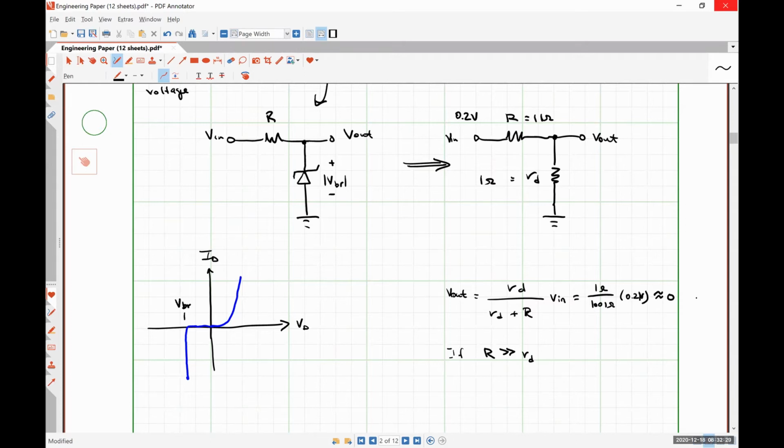So instead of pinning it at 6 volts, it would go down to say 5.4 volts or so. Conversely, breakdown voltages greater than 6 volts tend to increase in magnitude with temperature, whereas breakdown voltages of about 6 volts tend to be nearly independent of temperature.